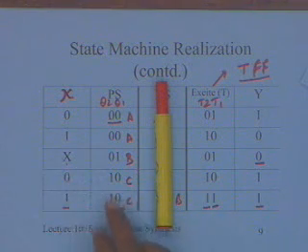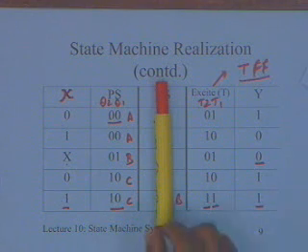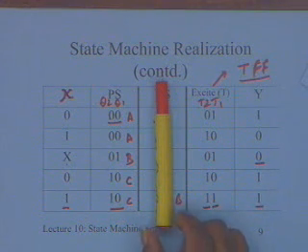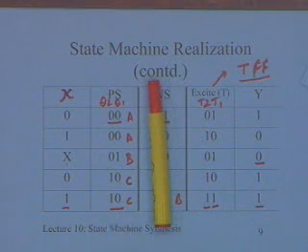So they are the 3 inputs and they are the 3 outputs, and you can use any of the minimization techniques that we have discussed before, Karnaugh map or Quine-McCluskey, and generate the circuit that is required for generating these outputs. Because I had 2 bits, there is something missing here: the encoding 1 1 is missing. So what do we do with 1 1?